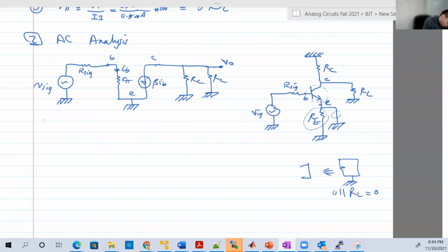Okay. So let's start by our input. Our input is that resistor between these 2 points, this point and the ground here. Okay, and it's really easy. It's equal to R pi, because again, this part of the circuit is isolated from that part of the circuit, because they are connected in just 1 point, which is the ground.